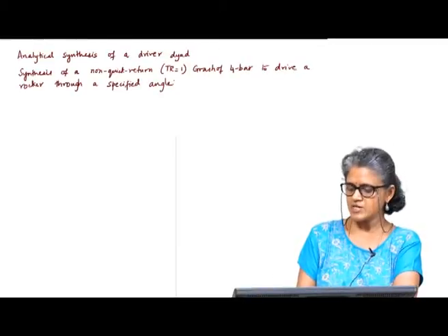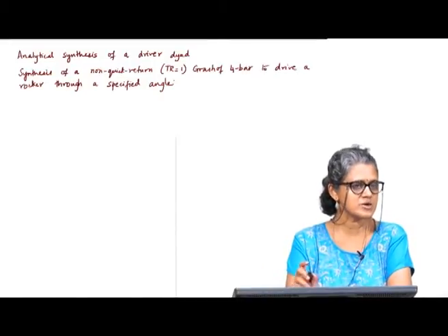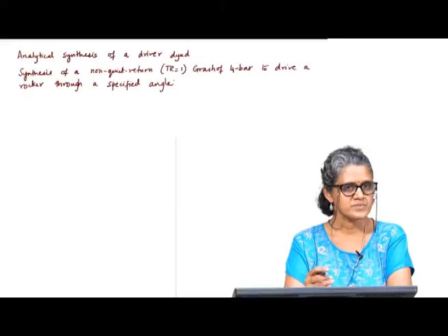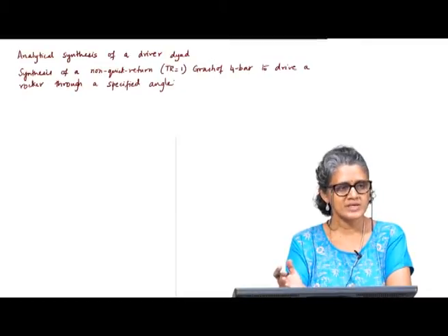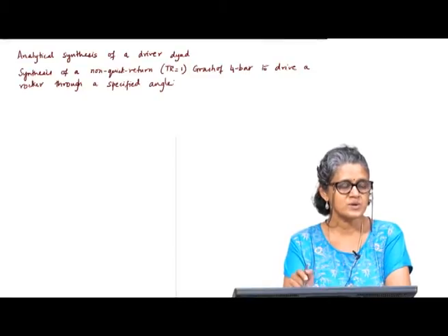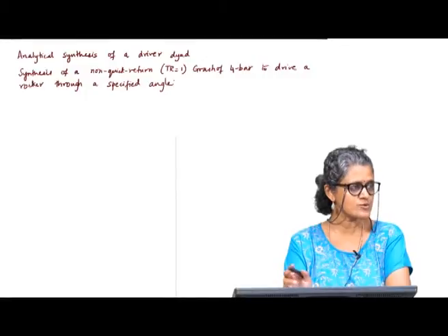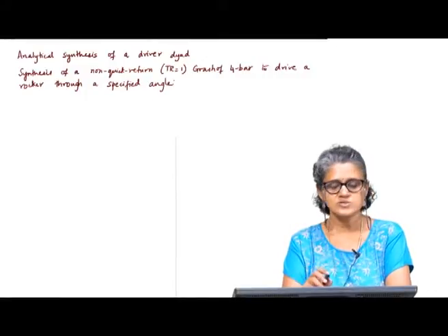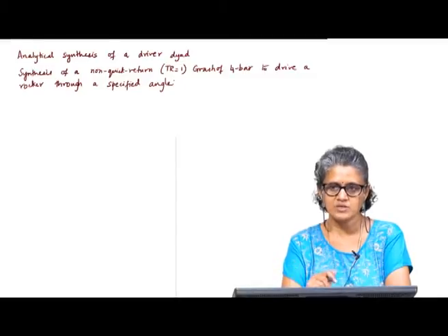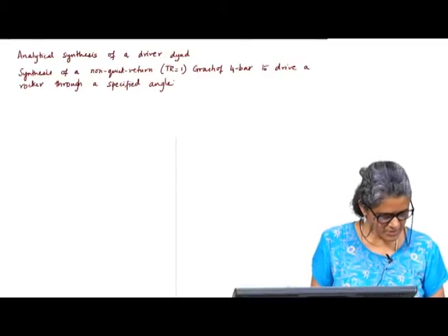So, practically usually your rocker movement should not exceed about 120 degrees. Okay. If you want more than that, you typically go to like a 6 bar. It is difficult to, because your transmission angles become very low. So, your force transmission is poor. So, practically you want to keep the rocker excursion, the rocker range to be less than 120 degrees or so.